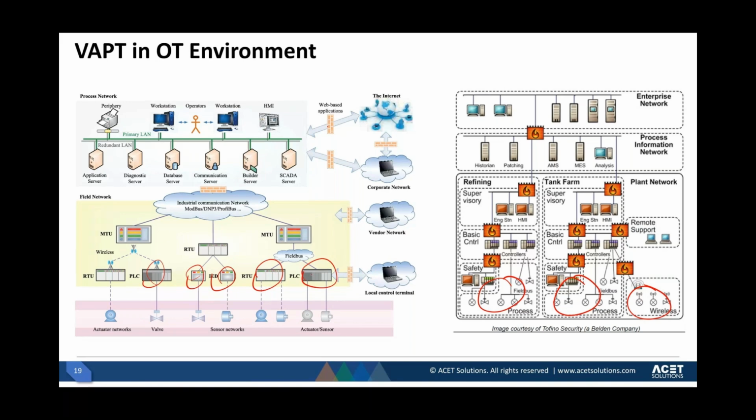I once found a lot of PLCs and RTUs had FTP and Telnet enabled, which were not even required for the operation of the control system.